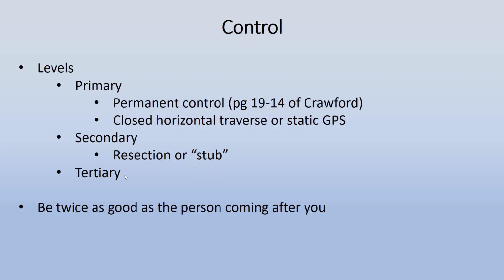So that's a good rule of thumb, is always ask the contractor, how good do you need to be with your caissons, or your pilings, or your well locations, or your manhole locations. And that lets you know what tools to use and what level of control you might be able to live with when you're staking things out for that contractor.